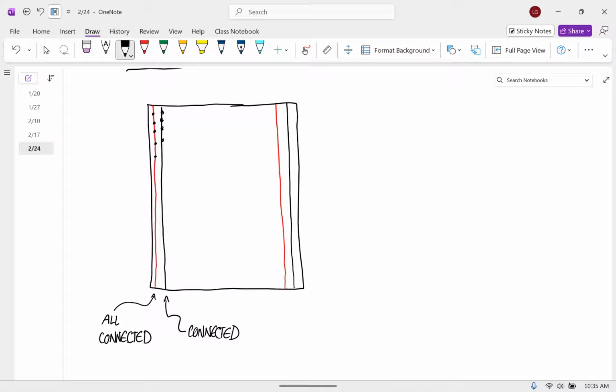And the reason the red and the black are there is because, as you start putting this stuff together, it can be kind of a hassle to take a battery and keep connecting it to places that you want inside the breadboard. So one thing that we're often going to do is take whatever our power source is, plug the positive of our power source into the red.